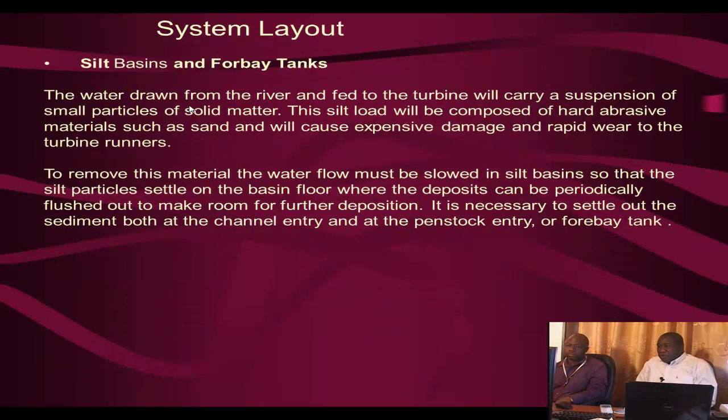Silt basin or forebay tanks. The water drawn from the river and fed to the channel contains suspended particles of solid matter. This solid matter is composed of hard abrasive materials such as sand that cause extensive damage and wear to the turbine runners.